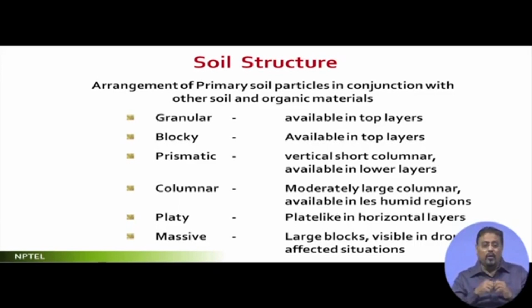But in the black cotton soil, what happens is this particular soil type is highly susceptible to expansion and contraction by the addition of water, and the soil particles are very fine in size, that means more clay within. So in such a case, the structure of the soil is very soft.